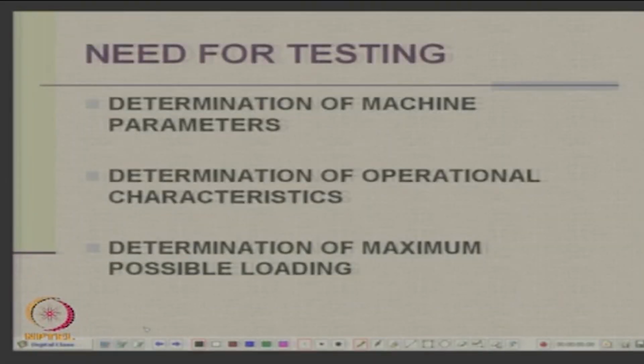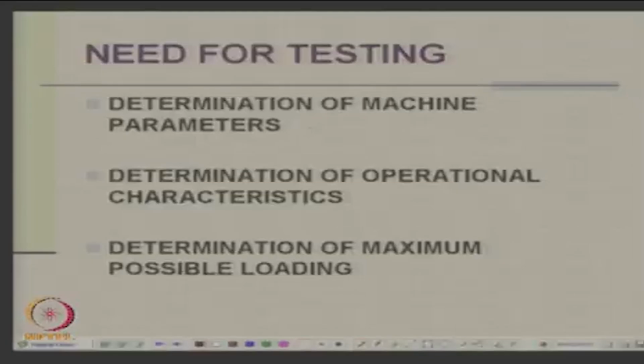And why do we need to do the testing? Because first of all, after a motor is made in a factory, why do you want to test? You want to test it because you want to find out its parameters. You know how it is modeled through the equivalent circuit approach, but how do you find those circuit parameters? That is one of the important objectives of conducting some tests, right.